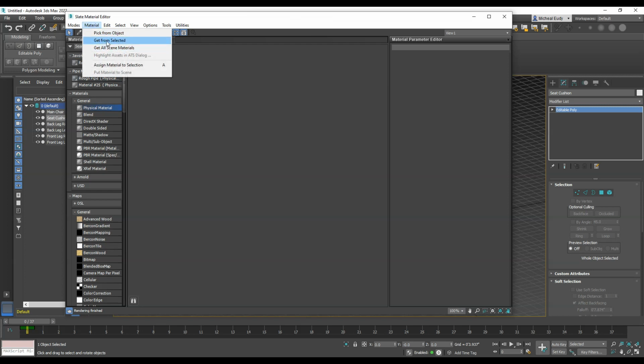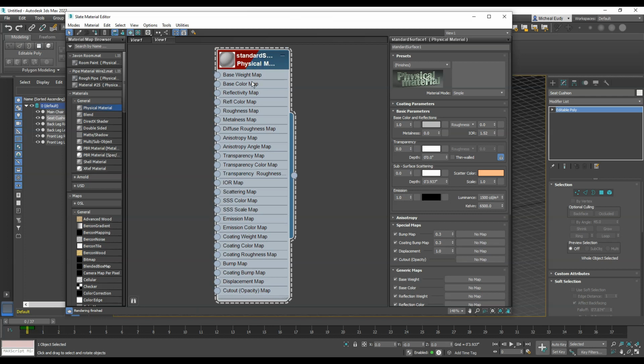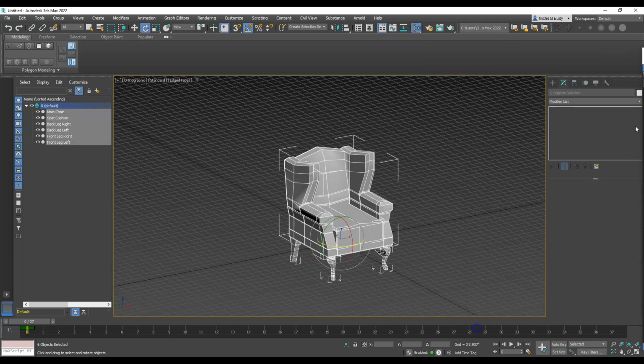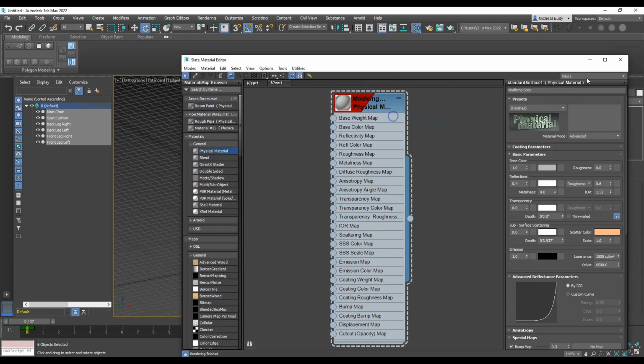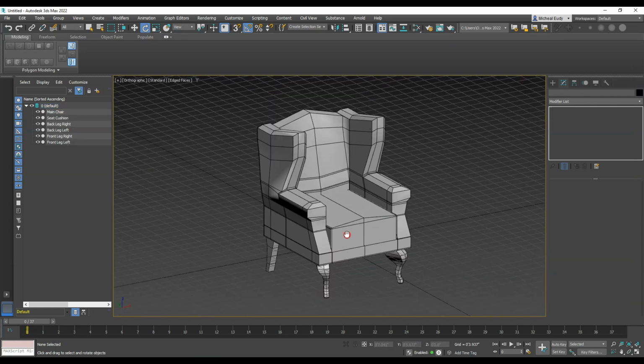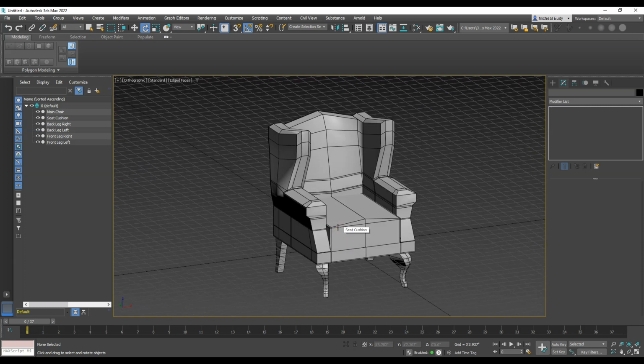So let's get the material that's on here, and that's fine. Let's name this. So we have, even though I can't spell, Advanced, and I don't want all this reflection on here. So let's do about a 0.4, and we want some roughness on this. 0.6 would be good. That'll give us a good shader in our viewport. And of course we want a black wireframe with this. Okay, so now this is finally set up correctly for me to deal with.